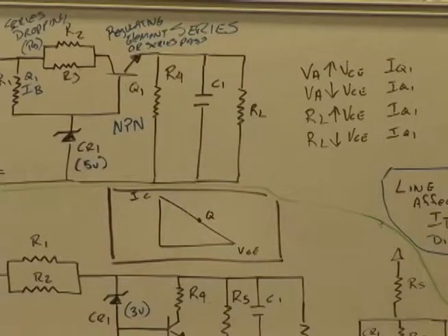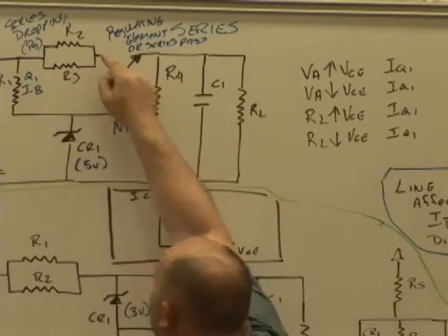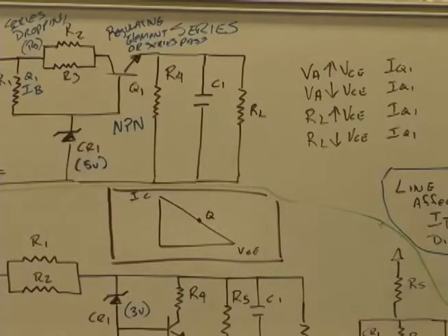Those are combined 34 ohms, aren't they? Like 68 ohm resistors in parallel, 34 ohms. How much voltage is going to drop? Next to nothing. So when it's time for the regulation process, I draw an arrow pointing to the right. Because you can prove it yourself. You should have when you did the lab. Go ahead and take your leads and place them across R2 and R3. Wow, that doesn't move. It's like 15 millivolts. That's why I do that, to make this a little easier, because this is relatively constant.